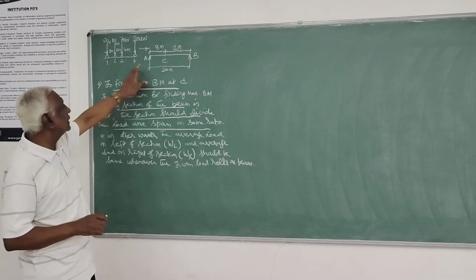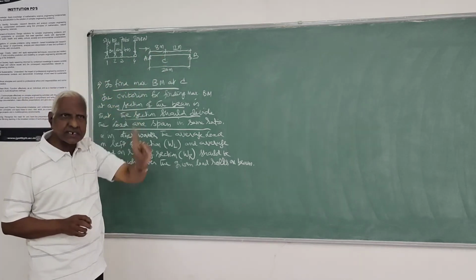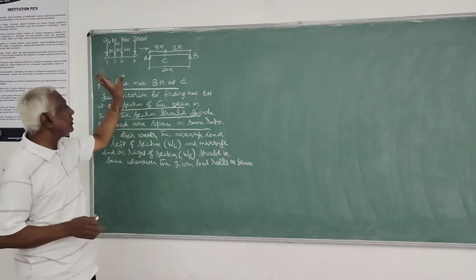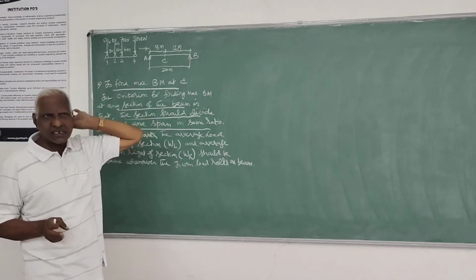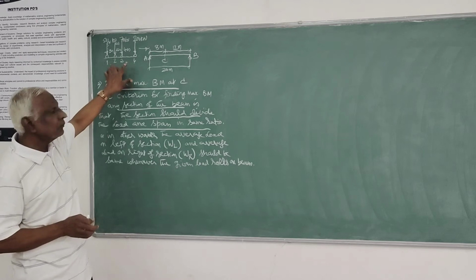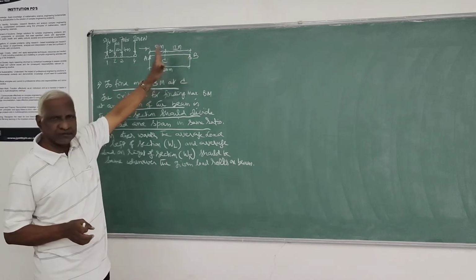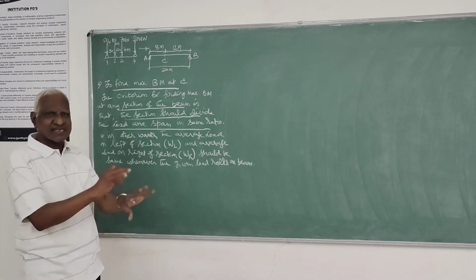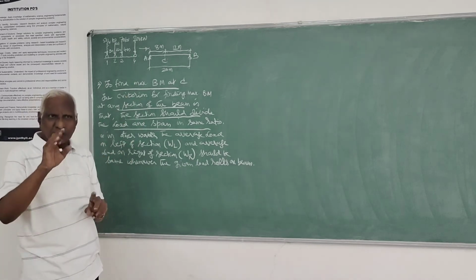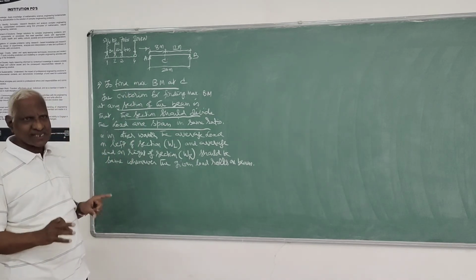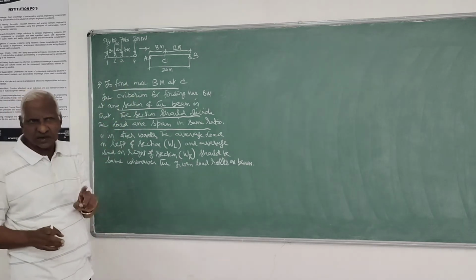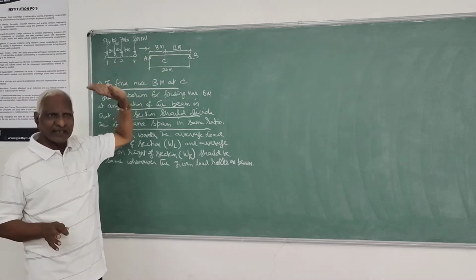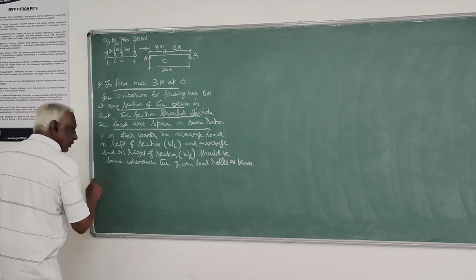Whenever you are placing for the first trial, you see that all the loads occupy the span. Here, all the loads will occupy the span only if you consider right to left. Otherwise, you do both cases and see that both results are the same. To avoid both cases, this is the shortcut which I have mentioned, to make sure all loads for the first trial lie on the span. So you just note that.